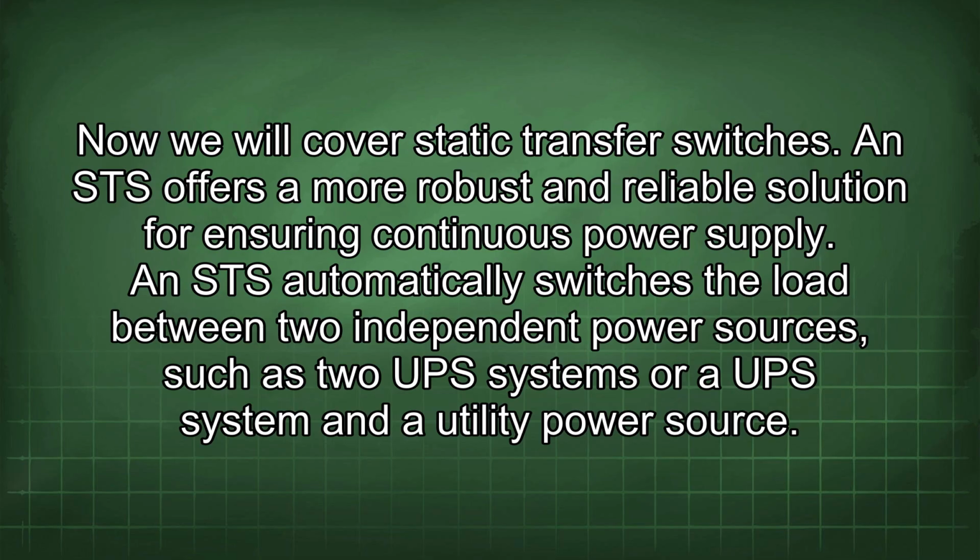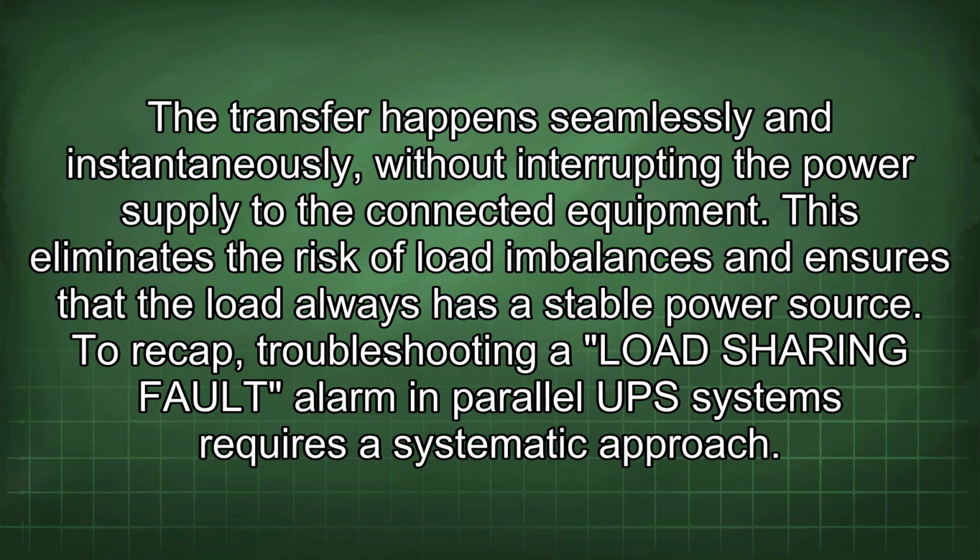Now we will cover static transfer switches. An STS offers a more robust and reliable solution for ensuring continuous power supply. An STS automatically switches the load between two independent power sources, such as two UPS systems or a UPS system and a utility power source. The transfer happens seamlessly and instantaneously without interrupting the power supply to the connected equipment. This eliminates the risk of load imbalances and ensures that the load always has a stable power source.